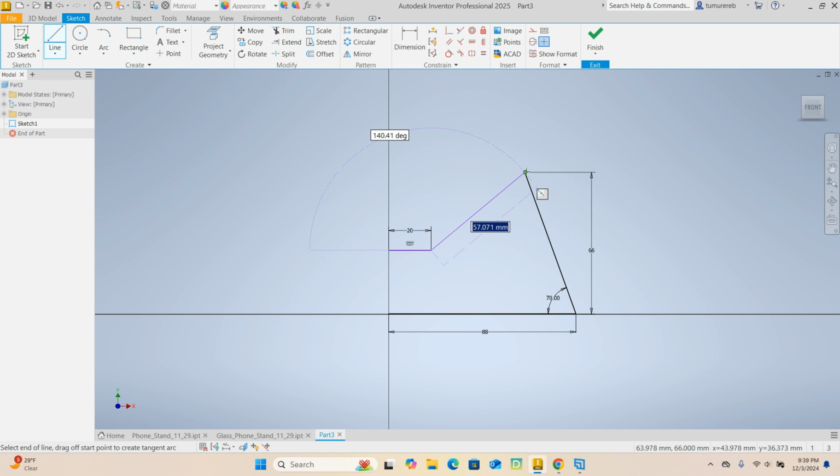And then let's go ahead and try to align with this part. Whenever you see that, don't click, just get that green dot and then move to your left. You're gonna see that reference line, and enter. Click anywhere is fine, and then escape twice, or right click, and then okay.